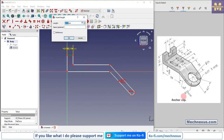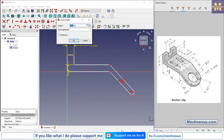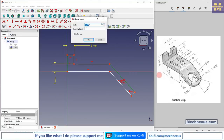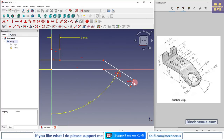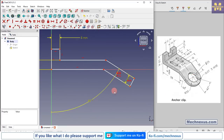Let's give this 8 mm, and we will move it, select this and add a vertical 8 mm, and select this line and add angular constraint of 60. Let's move it and select this line and click on dimension and give it 8 mm.